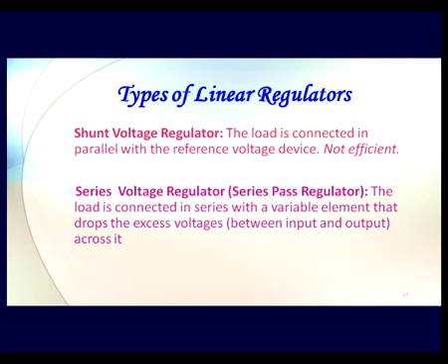In the series voltage regulator or series pass regulator, we connect the load in series with the variable element that drops the excess voltage between the input and output across it. That is called the series pass element, which actually does the dissipation part of it. But these kinds of circuits are very commonly used. Most probably you will always come across the series voltage regulators only, because they are efficient on the power side.